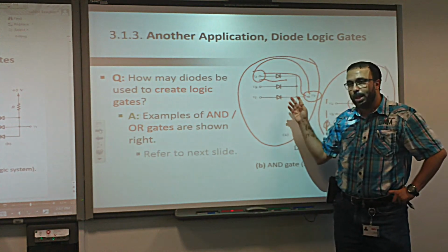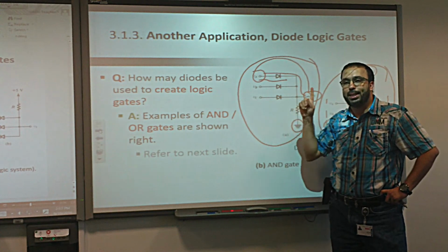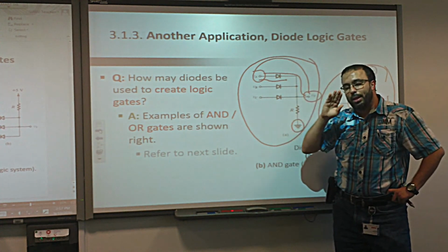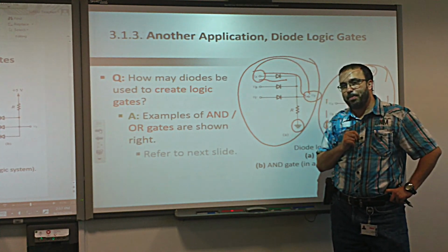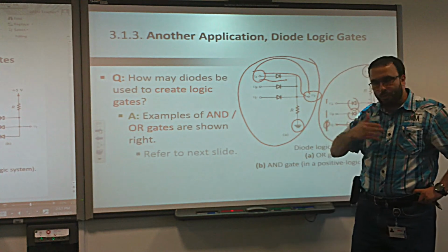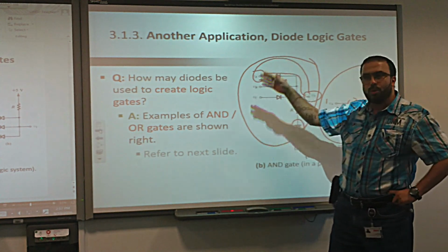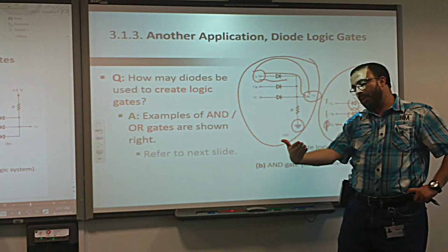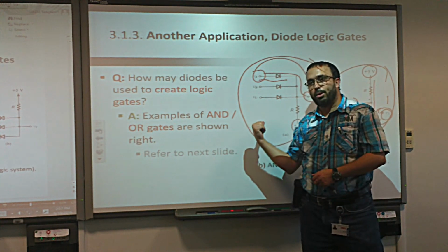Because for an OR gate, it can be high if at least one is high. So in real life, if you want to be really detailed, you go and try all 0, 0, 0. You apply all the possibilities here and you get the truth table, and you can look, is this OR, AND, or whatever. And you will know that this is OR.